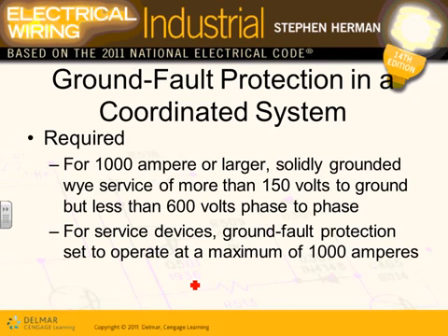The NEC would require, if your system is 1000 amp or more, and the voltage is 480/277, which meets this criteria, you are to provide ground fault protection, a special function in the circuit breaker, right here, ground fault protection, that looks at the ground fault only.